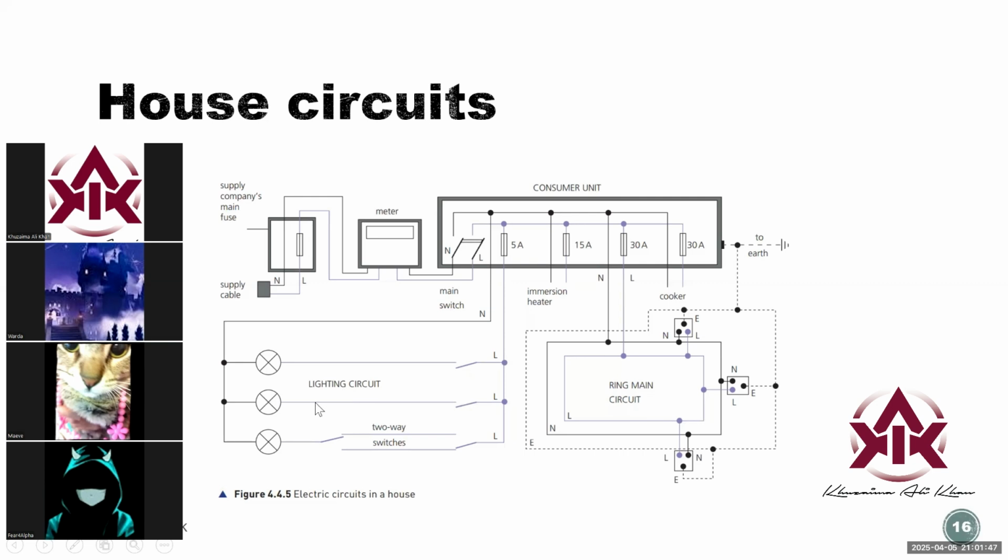So what is a lighting circuit? It just connects all of your light bulbs in your house, right? And you also have a earth wire here, right? You have an extra earth wire going to the ground and 10 feet down. So basically, just carry away extra charge which basically gets up on your plastic board or switch board and so on and so forth. Right? So we can see for every bulb we have a live wire, we have a live wire, we have a live wire, and back it goes back to the neutral wire, which is coming from the supply here, right?